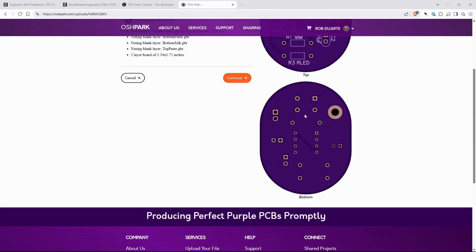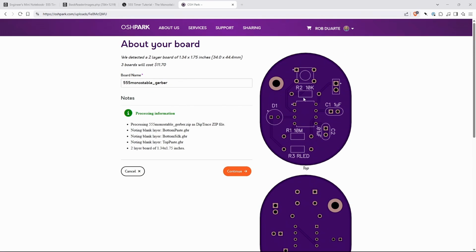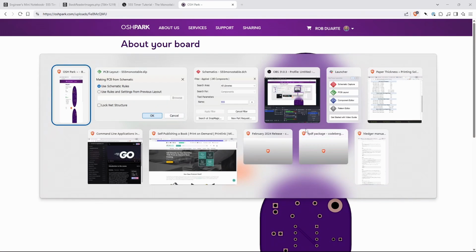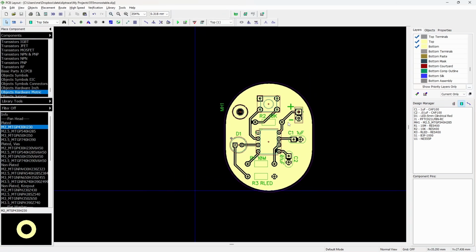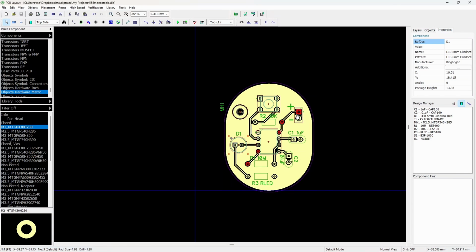And I didn't mention that you can just put text or images or anything on the Silkscreen anywhere you want. So this looks okay, but let's try and figure out why. I had this happen on another board that I made recently. This should be on the top silk, and it is. Curious. So I'm not totally sure why those aren't showing up, but what I can do is change this to